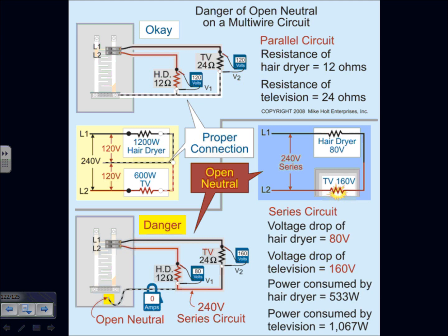So what did they do? I opened the neutral right here. When I opened the neutral, there was a fan right here, and a light. Exactly the same scenario, I'm not kidding you: a fan and a light that happen to be on the same circuit. So the exhaust fan in the corner got lower voltage. It was supposed to get 120, say it got 60 or 80 volts. It was running at the time.